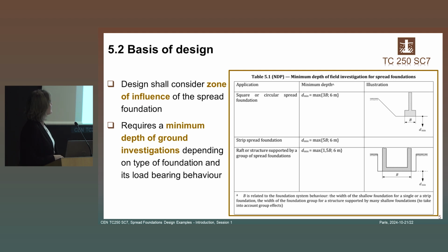And this needs to be considered in regard to the minimum depth of the ground investigations, whereas the type of investigations and also the number of investigation locations is established according to Part 2. The minimum depth of the investigations is specified in Part 3 for the relevant structures.